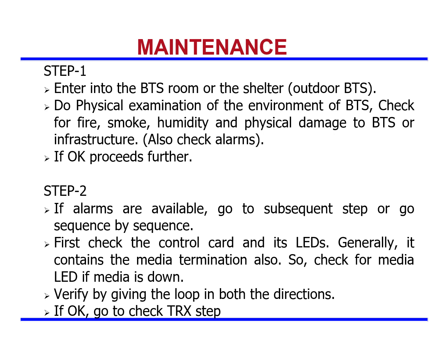Maintenance. The important steps are: Step 1. Enter into the BTS room or the shelter. Do the physical examination of the environment. Check for fire, smoke, humidity, and any physical damage to the BTS or the infrastructure. If everything is okay, proceed to step 2. If any alarms are available, go to the subsequent step or go sequence by sequence.